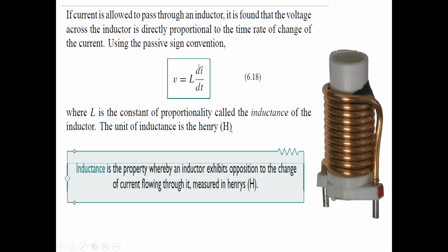So again we can use this equation to know why the inductor opposes sudden change in current. Let's say current is flowing at 2 milliampere, and suddenly, within no time, it tries to change from 2 milliampere to 2.5 milliampere. The slope of the current line will be infinity, meaning di/dt will be infinity, and hence the voltage across the inductor should be infinity, which is not practically possible.